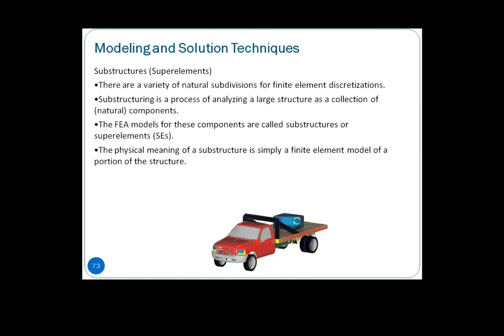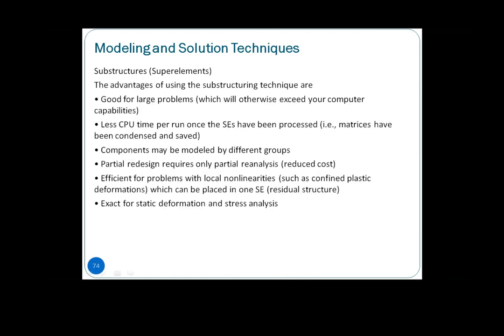The advantages of using the substructure technique are that it is good for large problems. If you have a very large model and it exceeds your computer capabilities, it cannot complete because it is too large and too heavy. Then you can analyze by parts or by components. In this case, you will have less CPU time per run, which will save you time and space.